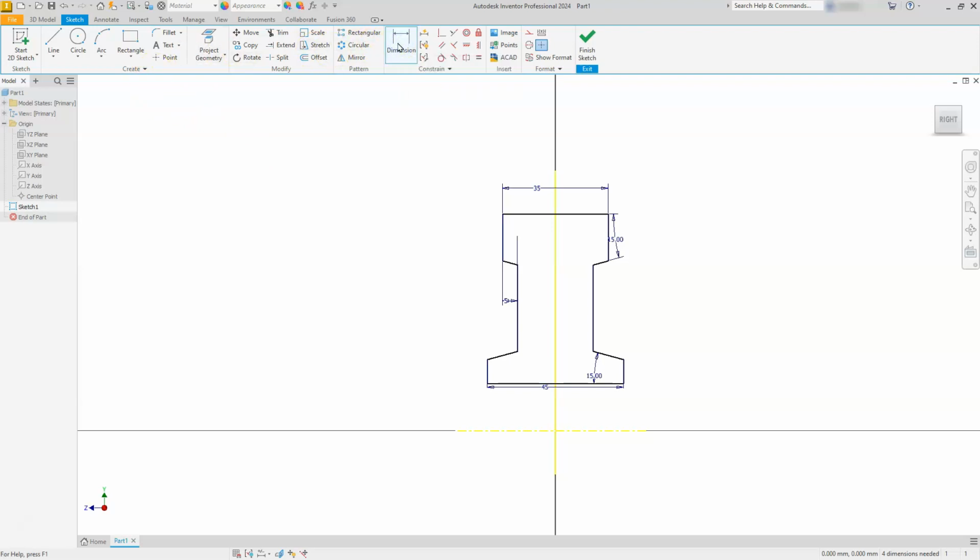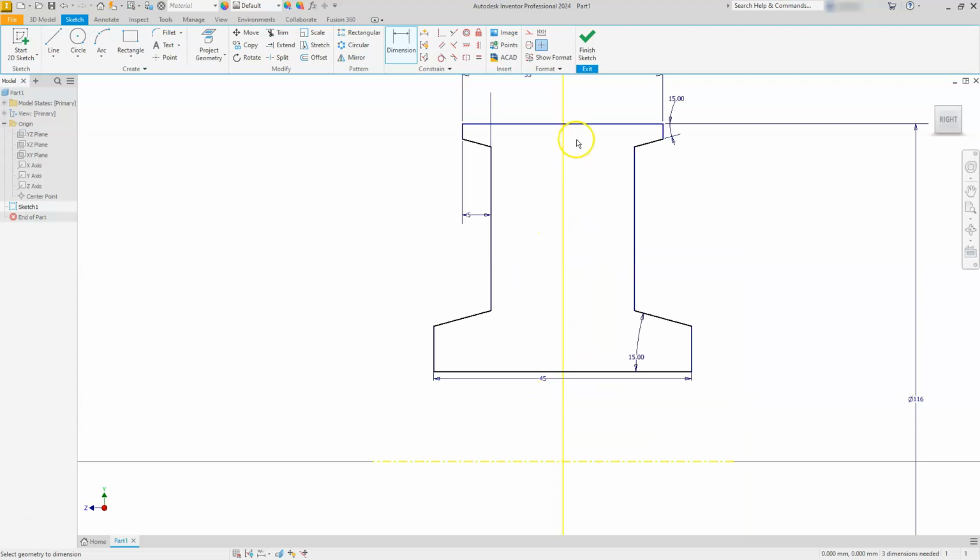And I'm going to start with my furthest dimension up just so these don't kind of overlap, and it still might pull downward. But I'm going to choose a diameter dimension, just a regular dimension. I'm going to select this top line, and then I'll select this line here that I just changed. And when I click here, you're going to see that now it's giving me a diameter dimension. Okay? Now this dimension needs to be 1/16. It's going to kind of squish this down. That's okay. Now if yours go underneath here, that's still fine with it.